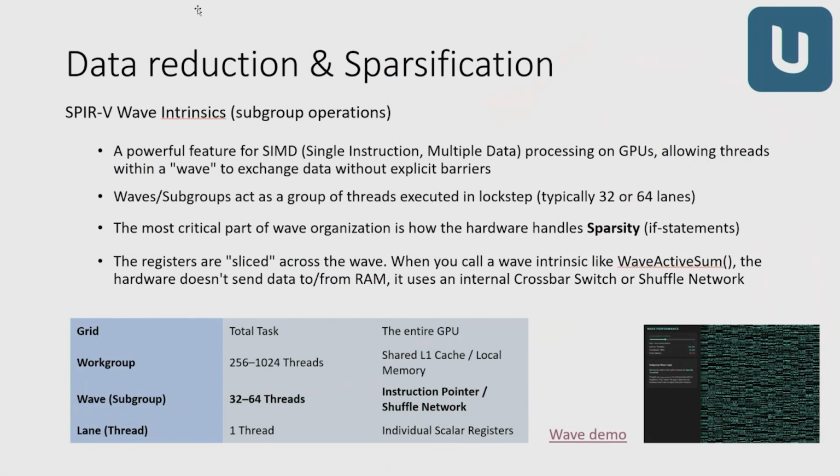So I'm going to talk specifically about intrinsics and wave intrinsics. So intrinsics being operators over a set of pixels, which is a horrible thing to do in general, because we have multiple images captured and those images have correspondences and we want to sample across that whole set of images. And the idea of the wave, or otherwise known as a subgroup, is you can basically have the GPU keep all those coordinated, so the access to the memory of those images is synchronized to the kind of pixel area that you're currently sampling.